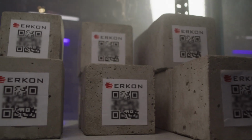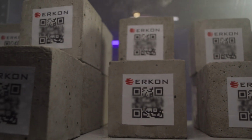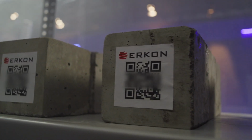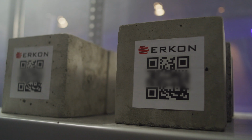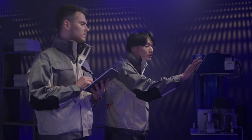Why at this particular time? Because concrete, according to GOST standards, must have a certain level of strength just on days 3, 7 and 28, and the intermediate period, day 14, was introduced by the specialists of the Erkan company independently in order to check the regulatory indicators more accurately.